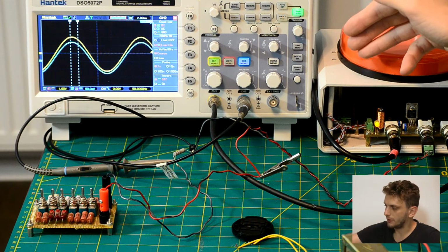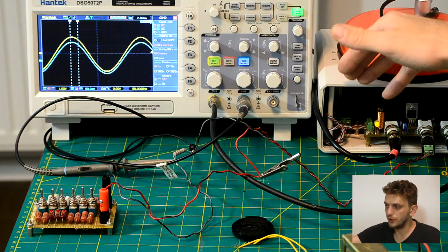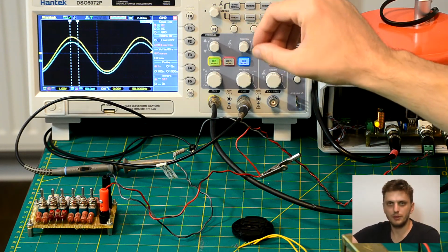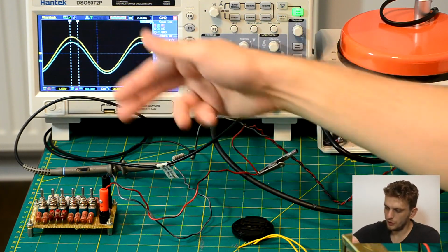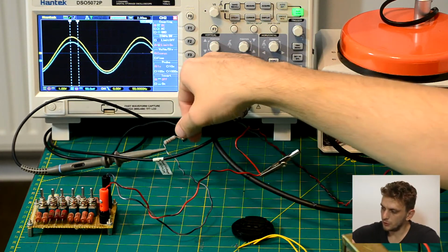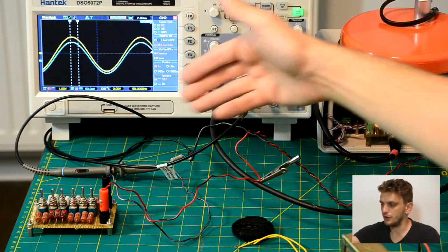Now, to understand the power factor, we need to look at AC current and voltage and how these behave when a generator is supplying a load. What I've got here is my power amplifier, which is supplied from the signal generator, and it's outputting a sine wave at 50 Hz, which is the yellow line, roughly 4 volts peak to peak. I'm using this voltage to supply a resistive load, so basically a resistor, and at the same time using a 1 ohm shunt resistor and the blue channel,